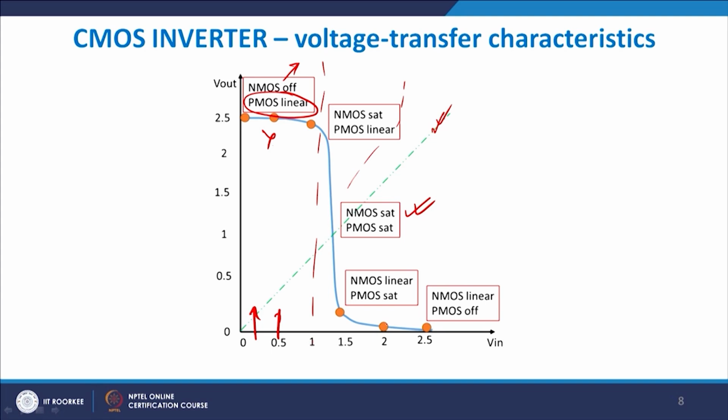other variables. Now, let me explain the basic MOSFET inverter principles, as I discussed with you; they are divided into 5 regions. The middle region, which is the green one you see here, is highly unstable, because a small shift in the input will result in the Q point shifting either to the top or to the bottom. Top or bottom means this point or this point.